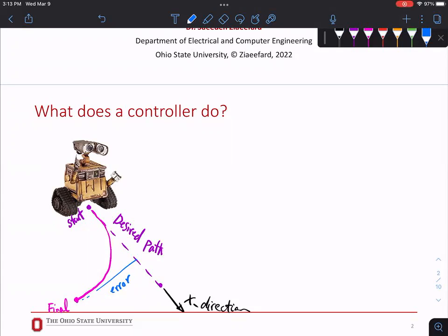So we need to control the velocity of the wheels, right? So that's one problem. If we fix that, what do you expect to happen? It was going straight, or from the beginning it started sweeping off but still going straight, but the heading is not what you expected, right? So then it needs another control to fix the heading. You fix the curved line, and it goes straight.